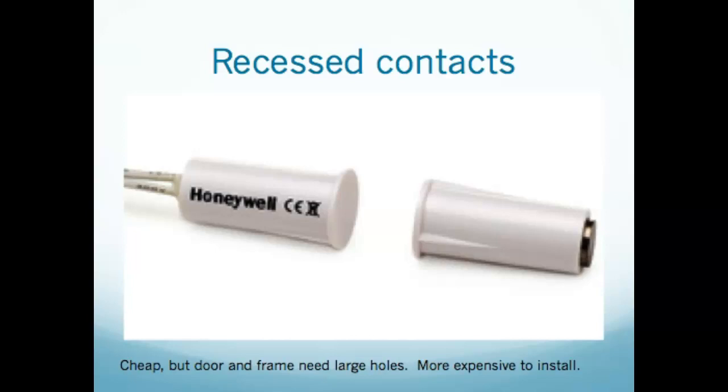But if you go around, even campus, you'll see these, I'm sure. If you look, when you open up a door that you assume to have an alarm on it, you'll be able to see just a little plastic circle on the opening side of the door on the top of the door frame. You'll look up and you'll see it. And if you reach up on the top of the door, you'll feel this one. And these two are the magnetic contacts that are facing each other with the reed switch going this direction, if you will. And the wiring is completely protected.